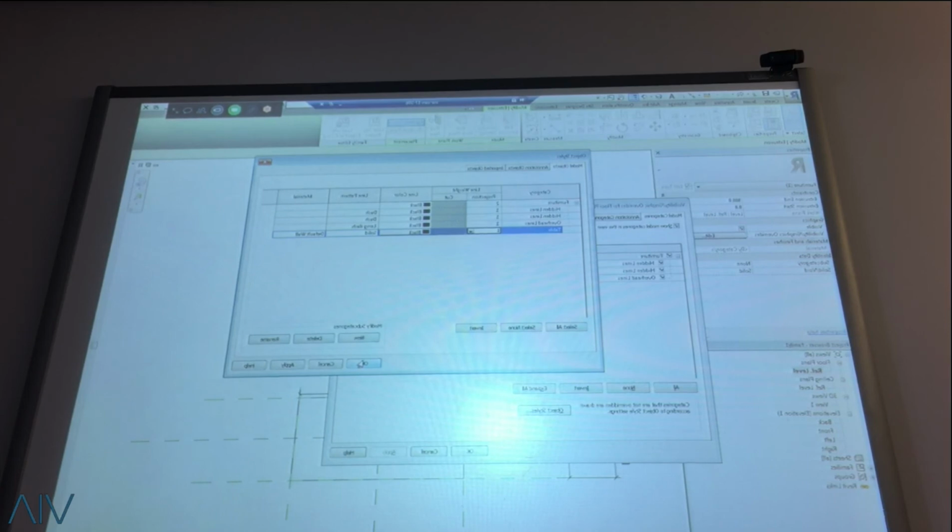Currently there is none, but you have to keep in mind the line weights. I want to reduce them as much as possible. You want at least five, but no more than that, because the more you get into it, the more you have to manage. Revit gives us 16 different line weights, but I think five is plenty. You don't need more than 5.